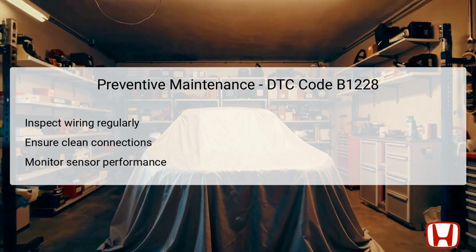To prevent the recurrence of DTC B1228 and maintain optimal performance of the climate control system in your Honda Accord, regular maintenance checks are essential. Start by inspecting the wiring related to the outside air temperature sensor frequently. Look for signs of wear, fraying, or any visible damage that could lead to shorts. Ensuring clean and secure connections at all connectors is also crucial, as dirt or corrosion can lead to intermittent failures.